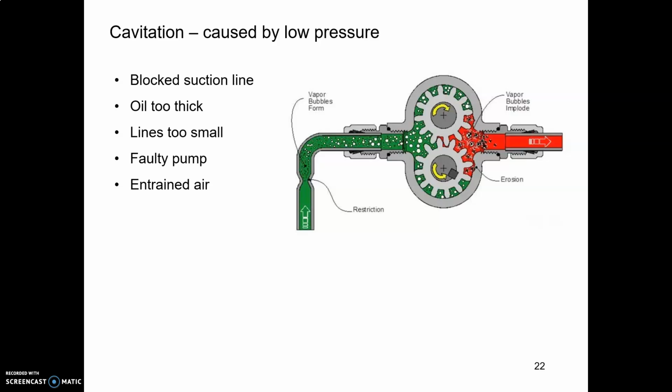And the people who do the troubleshooting are going to be looking for things like, well, is the line blocked? Maybe the oil is too thick and it's not moving through the line. Maybe it's not moving through the line because the lines are too small or something happened to restrict the line. Or maybe you've got too much entrained air, or something's funky with your pump. Other people will be doing the troubleshooting, but it's just nice to be informed and know what's happening when you hear this loud hammering noise.